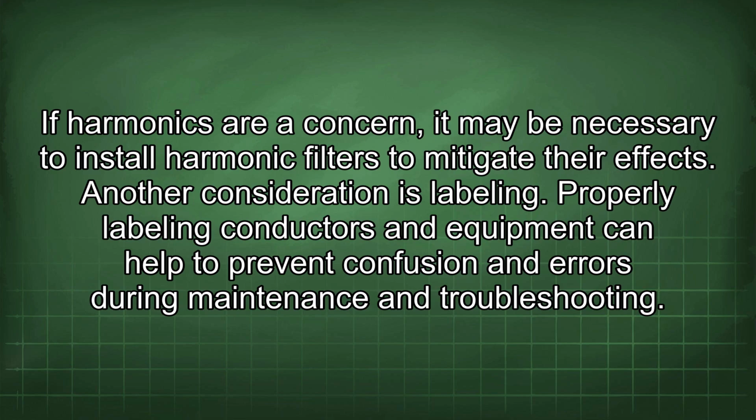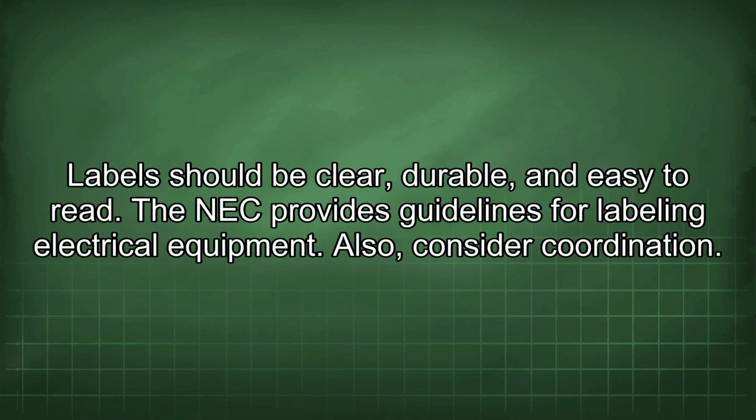Another consideration is labeling. Properly labeling conductors and equipment can help to prevent confusion and errors during maintenance and troubleshooting. Labels should be clear, durable, and easy to read. The NEC provides guidelines for labeling electrical equipment.